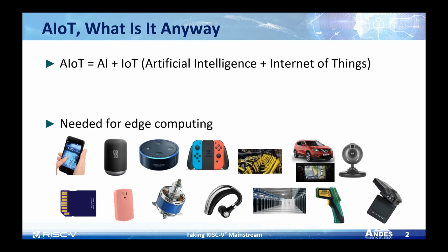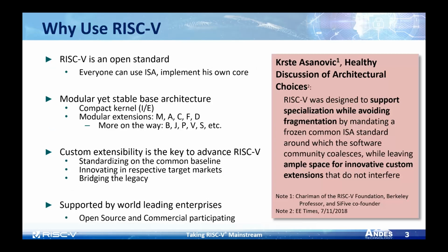More important question from my point of view is, why should you use RISC-V? Why not go with another established architecture? Well, RISC-V is a clean slate architecture, so you don't have any legacy. It's very easy to use. You have a well-defined standard with a common baseline, like the I or the E baseline, and then you have modules you can add. If you're adding certain modules or you leave them away, it's not breaking any compatibility. Your system still can run and your system is still compatible with the whole environment, with all the support from Linux, from GCC and other things.